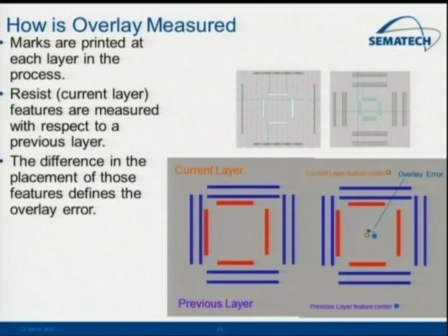This layer on the reticle, on the mask, you have another structure that's printed inside the same target. And then optically, you're basically measuring the difference between these lines. That can be done fairly accurately. And by comparing, therefore, the position of each of these lines, it gives you the displacement and, therefore, the overlay.